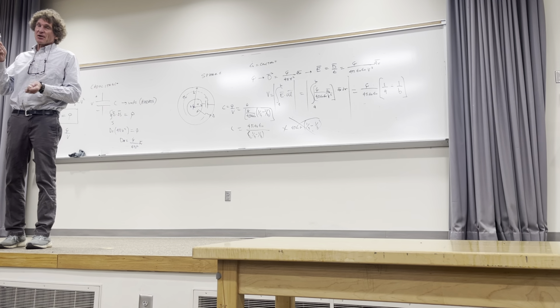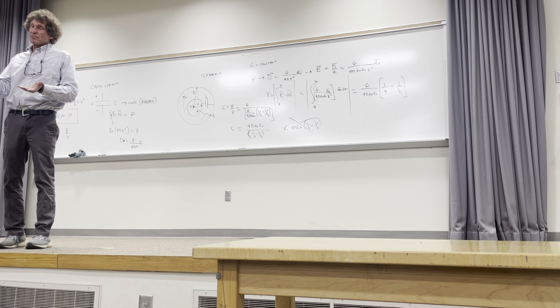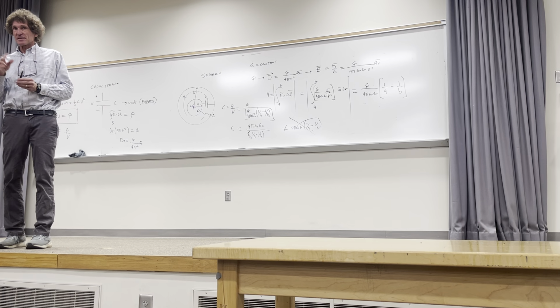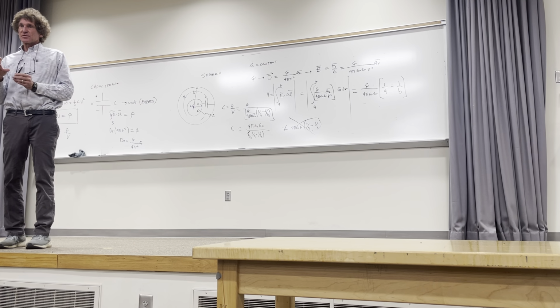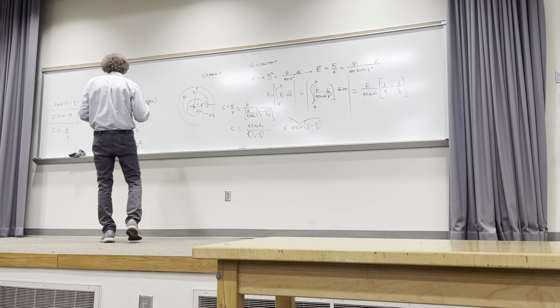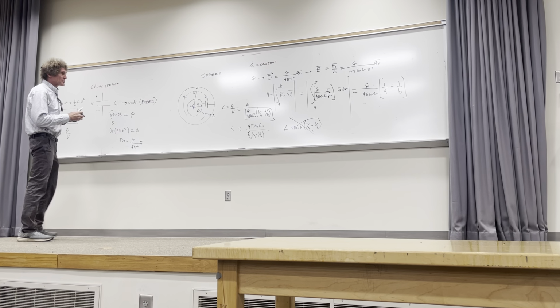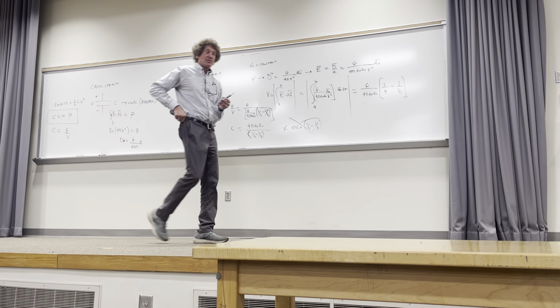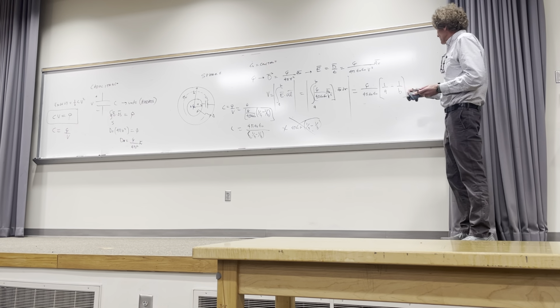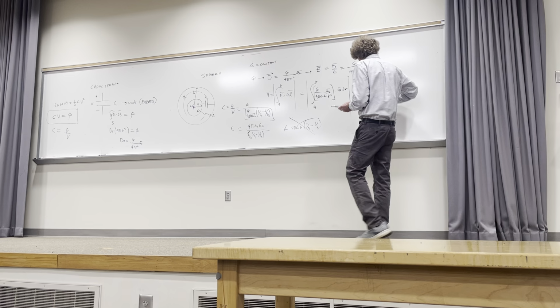You can discharge it. I mean, it does go bad if you break down the dielectric, but normal capacitors under normal use will not go down. They won't break down in your lifetime. Normal. I'm saying that cautiously because electrolytics will. They do have basically a goo in there that will start breaking down over time. Anyway, I'm giving you something to think about in terms of your future and maybe areas you want to get into. If you want to get into stuff like that, the automotive industry has got an open door for you because they're very interested in this.